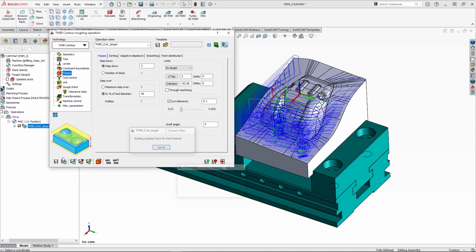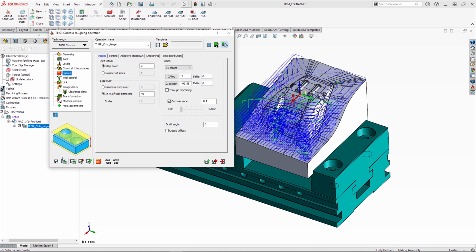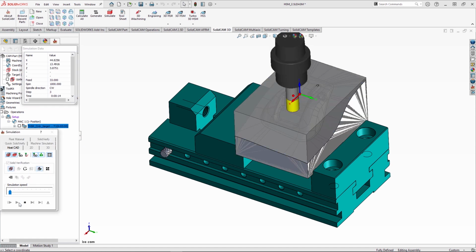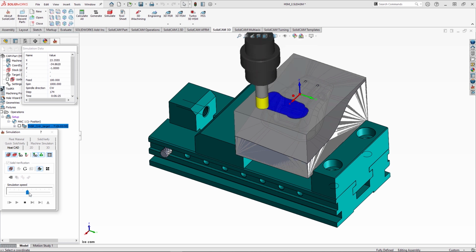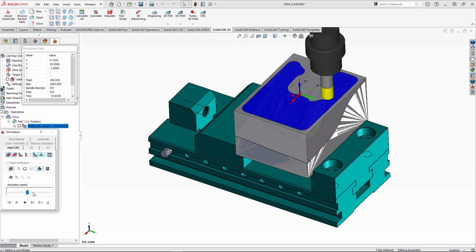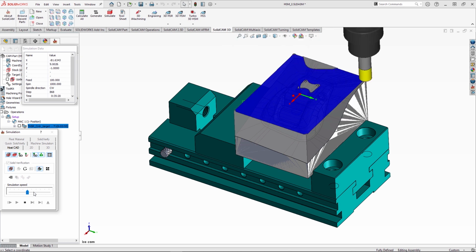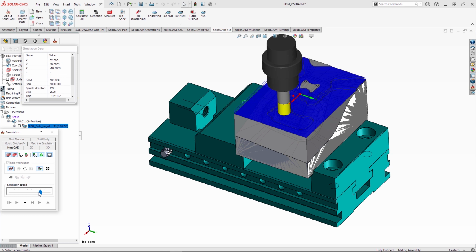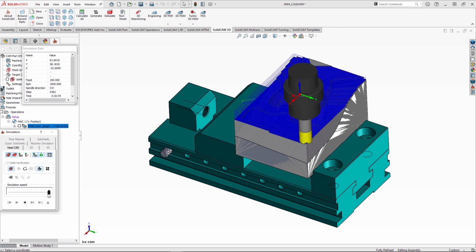You can see at the top of the part, I haven't got a toolpath, so I've added 2mm to the top. You can see that calculates quickly. When we go to simulate this, we can see this material will be removed as we increase the speed of the simulator. As the simulation progresses, you can see the tool working around the job to make the 3D roughing that we